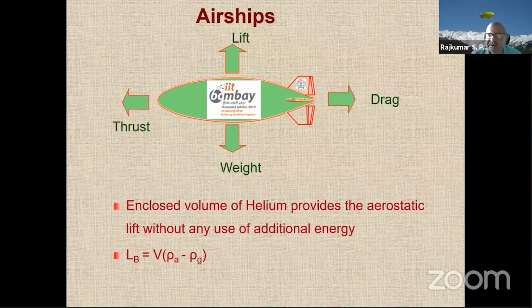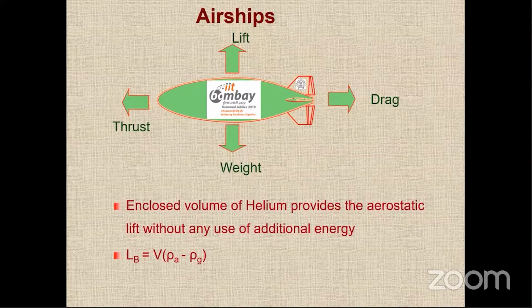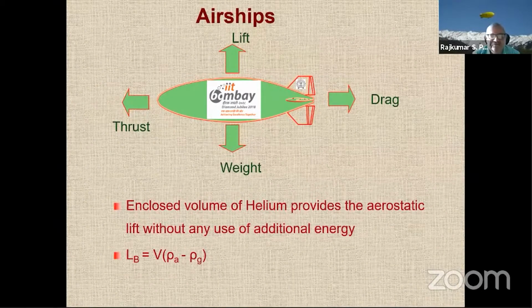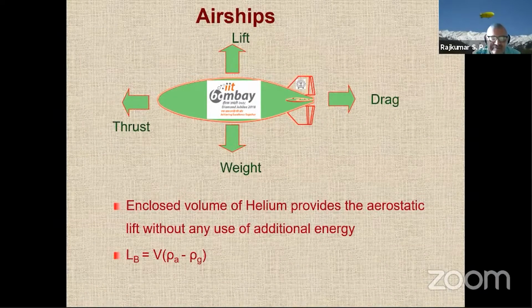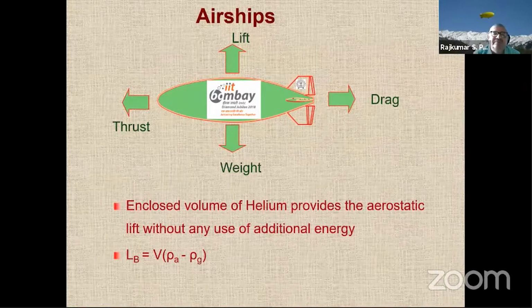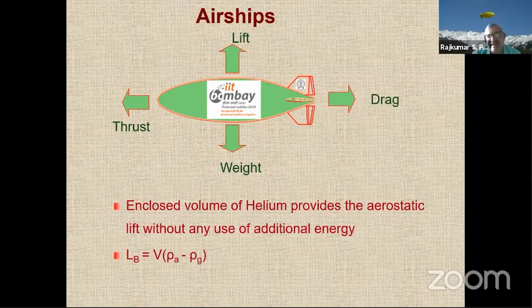Someone please tell me what is meant by payload in any aircraft. So the extra carrier weight other than which we can lift with our aircraft. Other than the self weight, correct? Yes, sir. So from the buoyant lift LB, if you subtract the self weight, what will you get? Lifting capacity. And you can use the entire lifting capacity for payload, but then you'll have no margin at all. You might say 80% of the lifting capacity I will use for carrying payload and 20% I will keep for something else. Or you might say 90%. It's up to you.